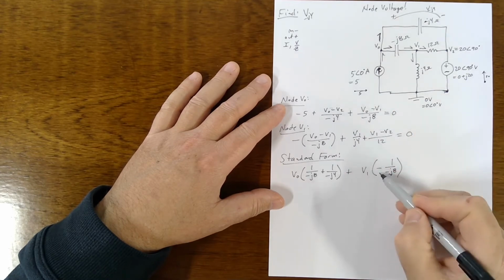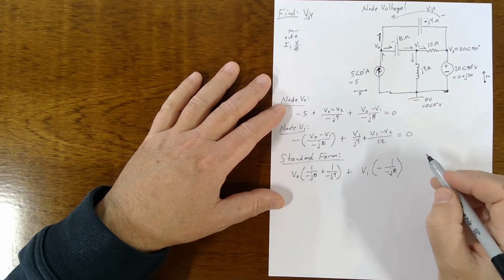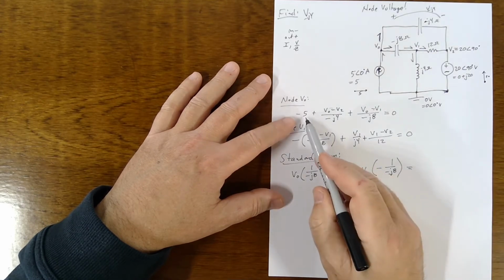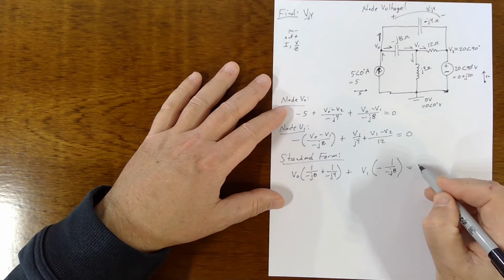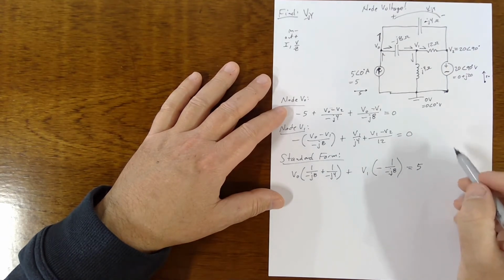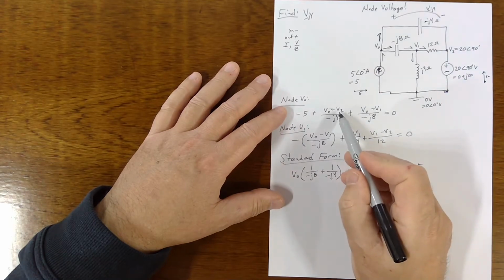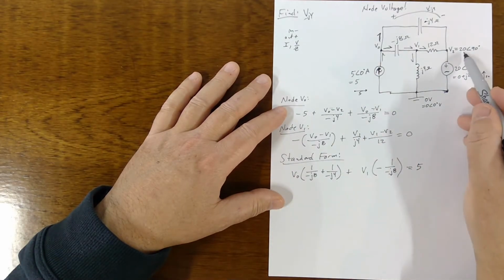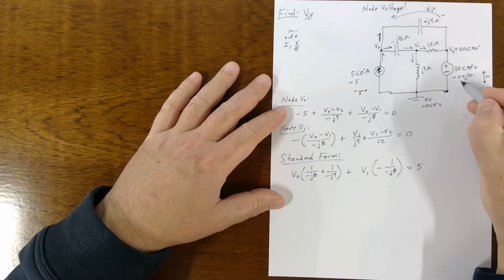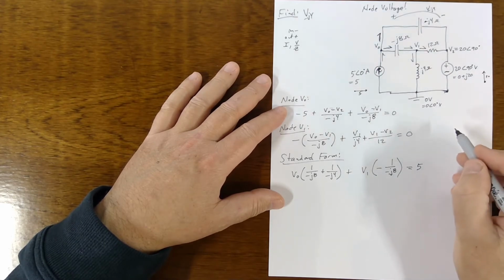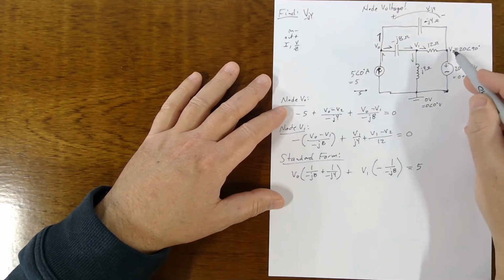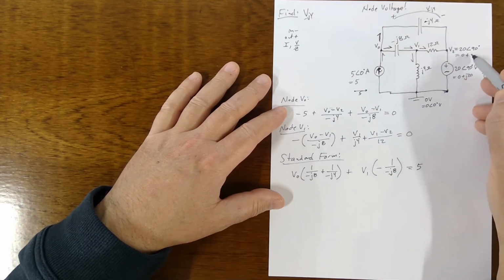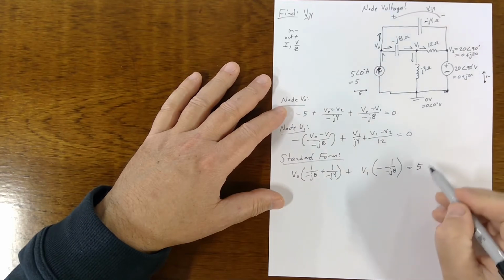There's a minus J, so there's a minus sign you've got to account for somewhere. This equals this 5. Pull that guy over to the other side, and it seems like I'm missing something. Oh, V2 is known, and V2 is this thing. It's 0 plus J20, right? 0 plus J20 equals V2 here. This thing is the same thing, 0 plus J20.